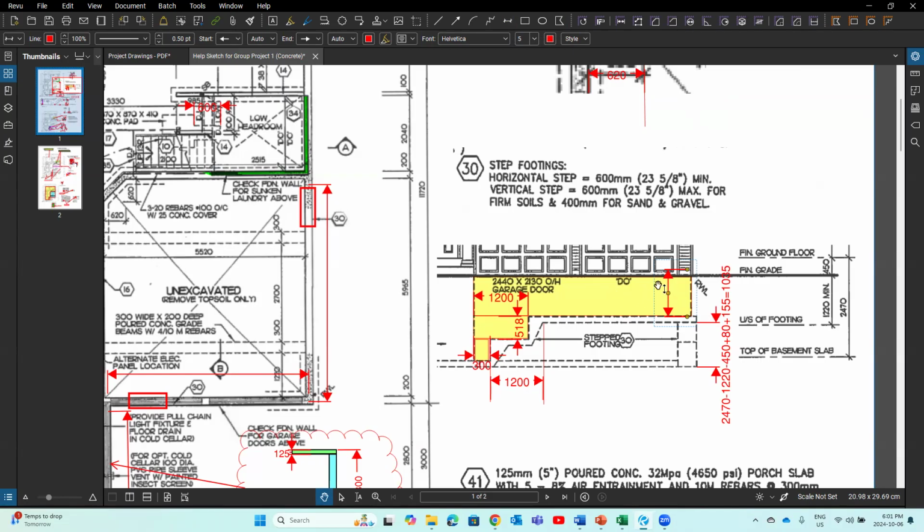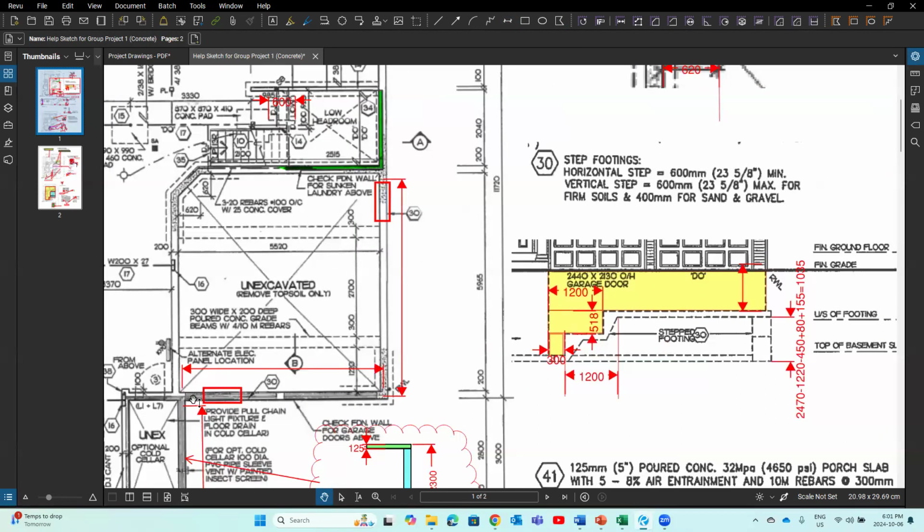So we are going to think about, take that dimension, right? We multiply by the length. So the length would be this length here, right? From the foundation plan. We will be able to get this area here, right? This area. And of course, there is a recess on top of the foundation wall, which is for the garage doors here. We need to subtract this, right? Then step footing. Okay, step footing here, we need to add this, right?